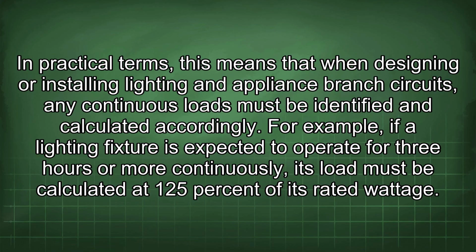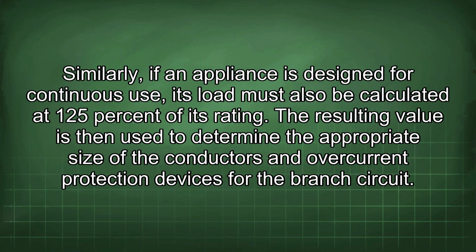identified and calculated accordingly. For example, if a lighting fixture is expected to operate for 3 hours or more continuously, its load must be calculated at 125% of its rated wattage. Similarly, if an appliance is designed for continuous use, its load must also be calculated at 125% of its rating. The resulting value is then used to determine the appropriate size of the conductors and overcurrent protection devices for the